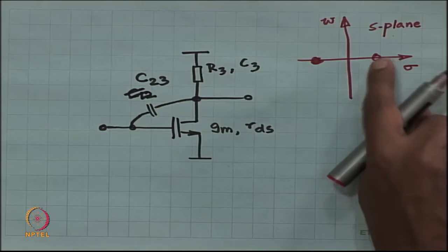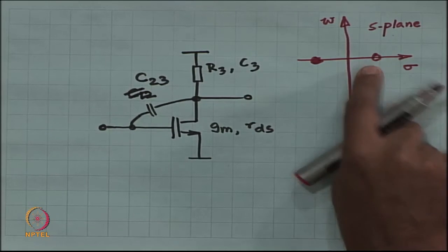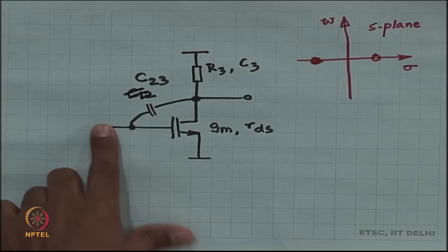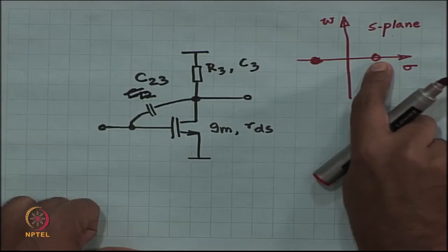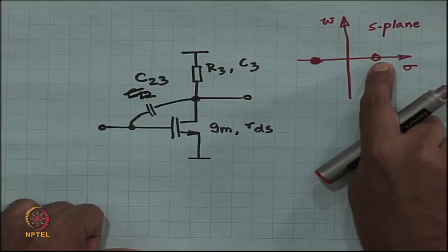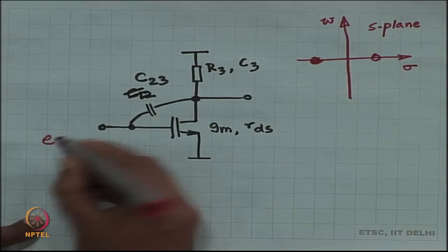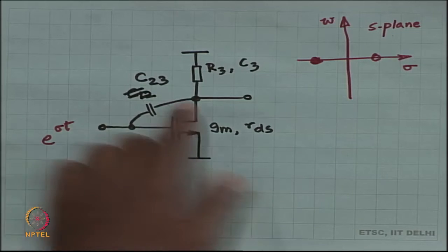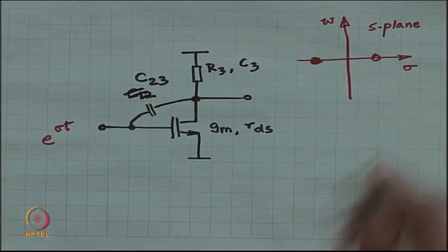And this is not really a so called frequency, it is some sigma, it is not omega, which means that the kind of input you have to apply is not a sine wave, you have to apply some kind of e power sigma t. So, if I apply a voltage over here looking like e power sigma t, then the response is going to be 0.